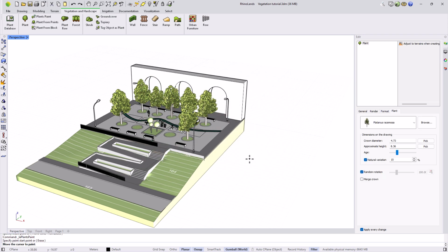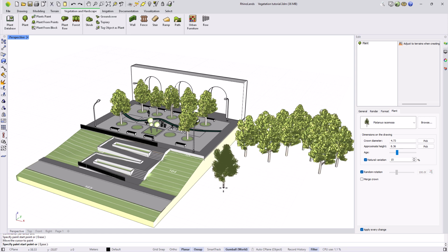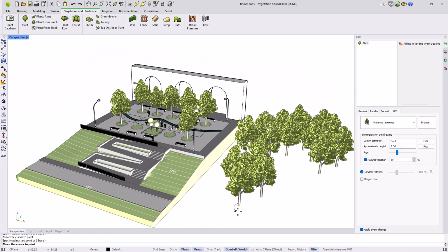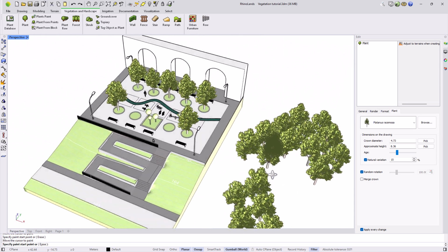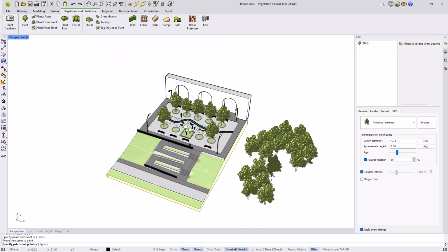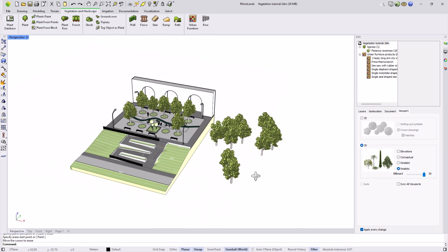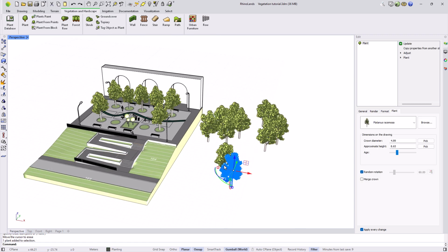With this method, we make a first click with the cursor, and until we make a second click or finish the command, plants will be inserted in a triangular matrix along the path where we move the cursor. With this command, we can also choose the delete option from the command bar to reverse and remove the specimens along the path where we move the cursor again. Once finished, we can also select these plants one by one to move, delete, or adjust some of their parameters.